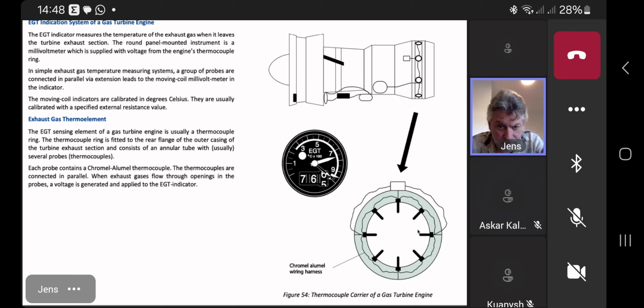So they're independent. But what you have to make sure is, maybe in case of repair of the wiring system, it's working also with resistance. So if you have the wiring to replace, you must use the same material in the wire. Of course, you work in accordance with the manual, but imagine you have those thermocouples here.